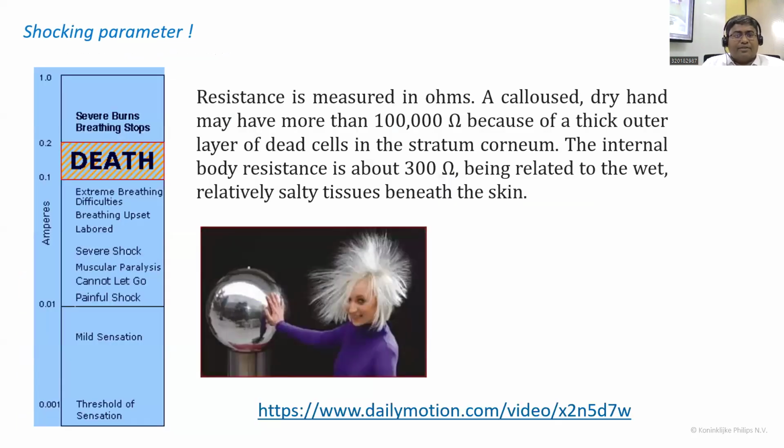Okay, so here are some facts on why people are so serious when we talk about high voltage. The first thing that comes to mind is shock. However, we all know in this forum that it's not the voltage, it's the current which is responsible for giving us the shock. Due to human body resistance, the amount of current which is really shocking does not depend on a particular voltage level, but rather on body resistance, which continuously changes from time to time.